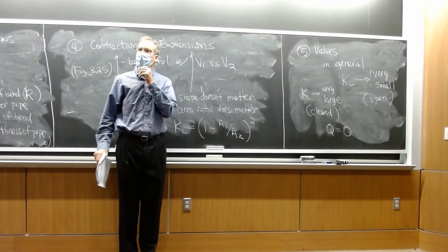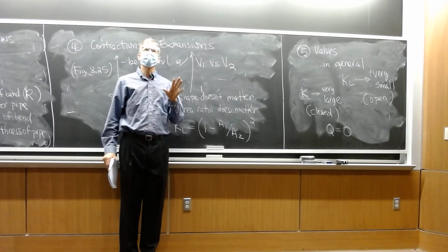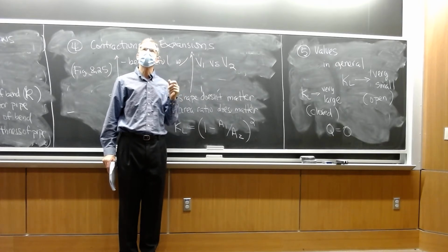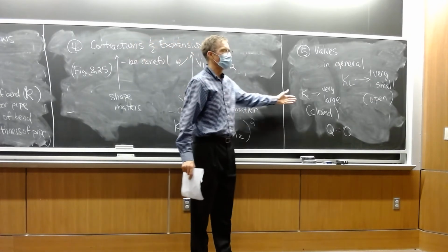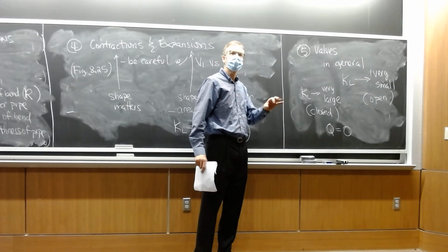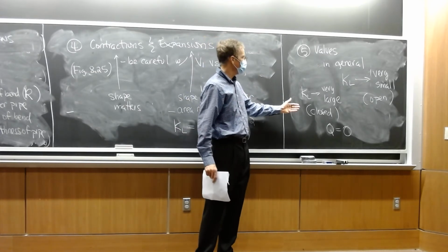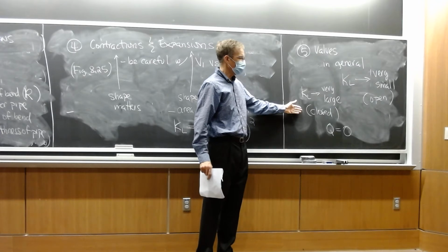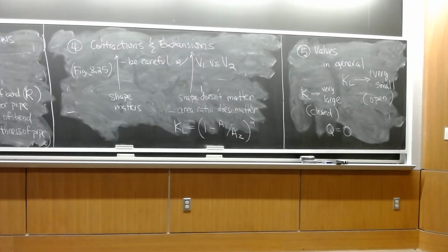Q is 0. So there was a question on that first question on the test. It said there's a flow restrictor that limits the flow to a particular value. You might do that by having a valve that's open to varying amounts. Then the head loss from that valve changes, and therefore the flow changes.